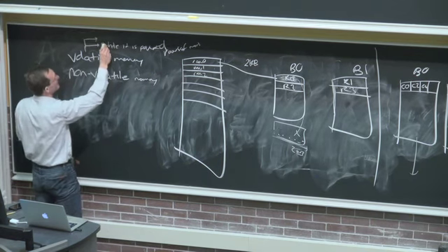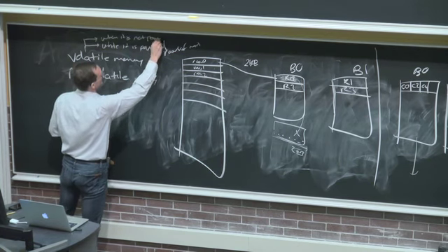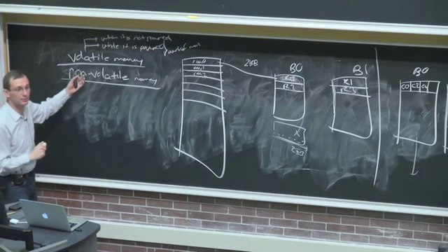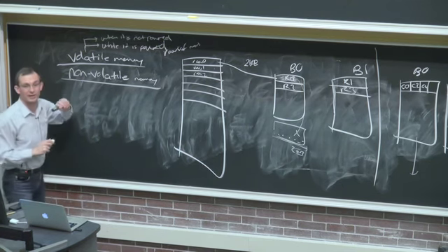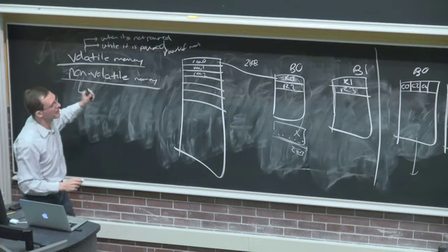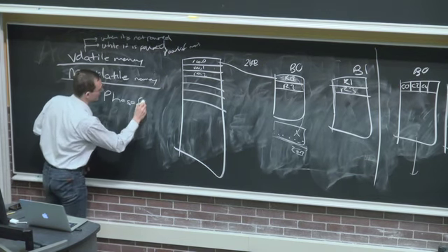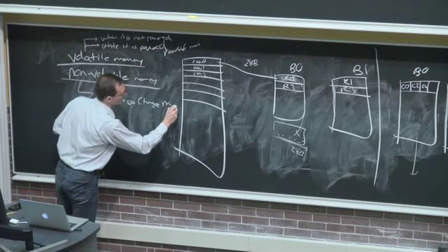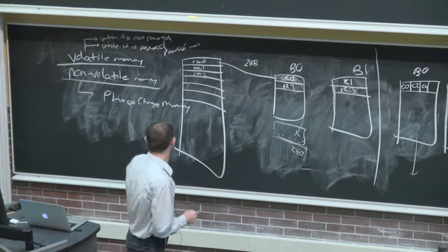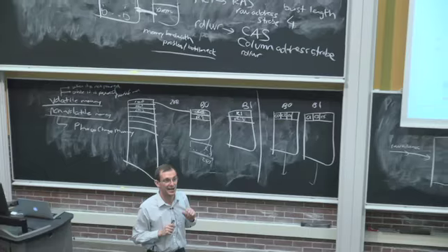And it also loses the data when it's not powered, right? And powered means you're actually connected to a power source. Whereas non-volatile memory, like a hard disk, doesn't lose data regardless of whether or not it's powered, right? So if you can build a main memory with non-volatile memory, like phase change memory, for example, or flash memory, then you don't have this problem, right? So that's one way of eliminating refreshes. The downside is there are downsides to these other technologies as well. They have much longer latencies to access.